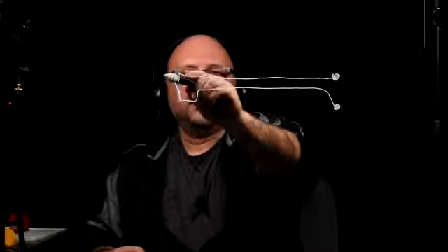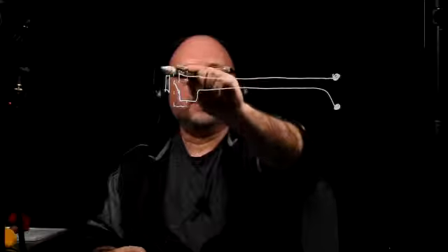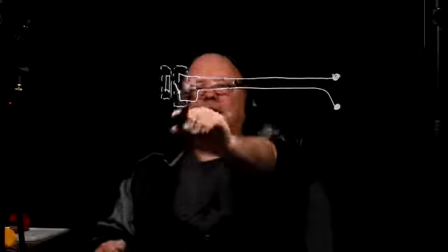There is a zone of an alarm system or a circuit, and it has a wire running from that zone, terminated on the other side in something called a reed switch for the most part, and there's a magnet. So this wired part is going to be part of the door frame, and this magnet is going to be mounted on the door itself.